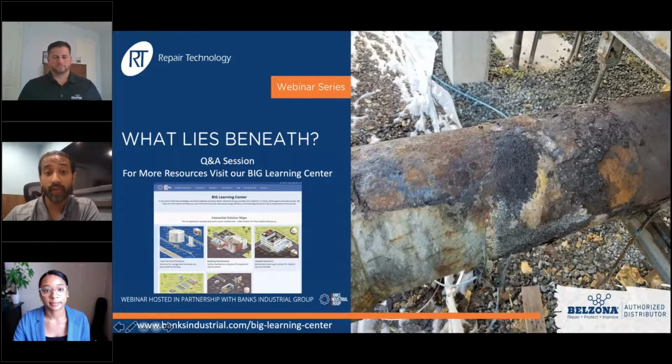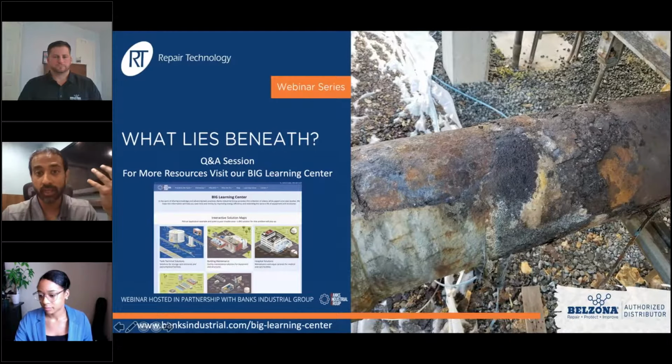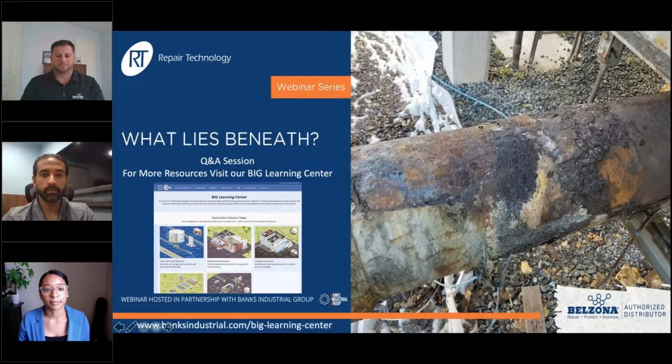One thing you can do, if I can add on there, Aria, is that in our previous webinar we showed an elbow that we had super wrapped. When we went back and took x-rays of it, you could visually see where you lost the barrier. So potentially an x-ray could help you with that as well. These have to be options.